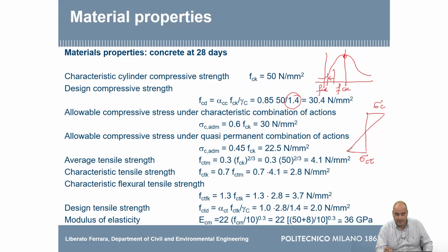It's true that when the concrete stress arrives at that limit, you start forming a crack. But the bent cross section has this advantage that you arrive at the maximum stress here, but you see you have another significant portion of the cross section which still can help. So you can have some cross-sectional stress redistribution.